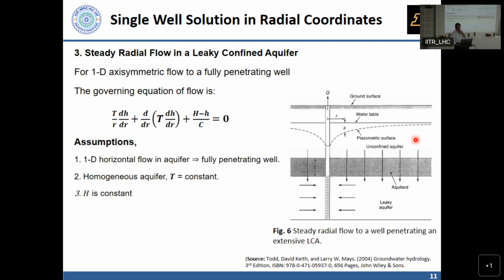What is the leakage actually doing? So what the leakage is doing is, if the piezometric surface on the other side of the aquifer is higher, it's going to pull water in. But as we keep going further and further away, notice that the piezometric surface in the main aquifer is rising. And therefore, as I keep going further away, the leakage rate is essentially going to be affected too. If it's going to achieve a steady state and be at equilibrium, this leakage will keep happening until both the piezometric surfaces on both sides are essentially the same, and then it will stop. And you have to go that distance to say, well, that is approximately what we would think of as the radius of influence. I'm sorry, my mic is going on and off because the battery is very weak.